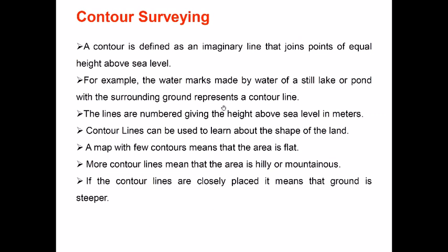So the lines are numbered, giving the height above sea level in meters, or it can be in feet. It is not a rule that it has to be in meters. And contour lines can be used to learn about the shape of the land. We discussed that.